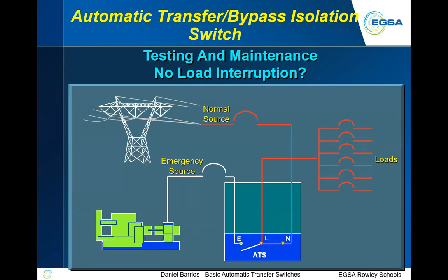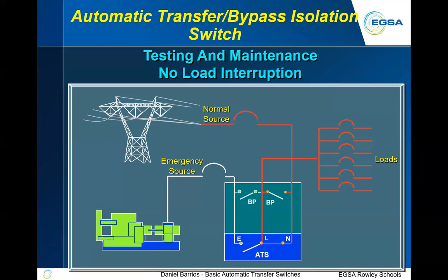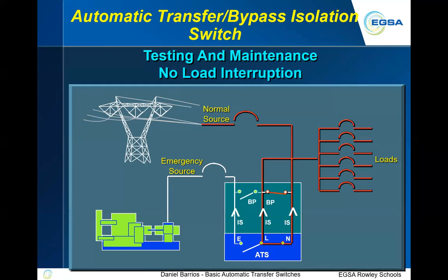So in this case, you're connected through the transfer switch, and that transfer switch is providing load. Now I add the second set of contacts, that upper portion, the bypass. When I close that, now I have two paths of current. The little V's, the little TP's there mean that that lower unit is a draw out type unit, as we saw in the picture. You can draw that out and no interruption of power downstream because you're bypassed.